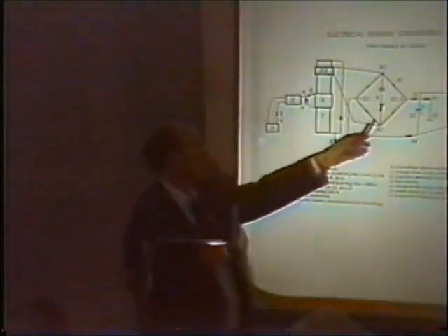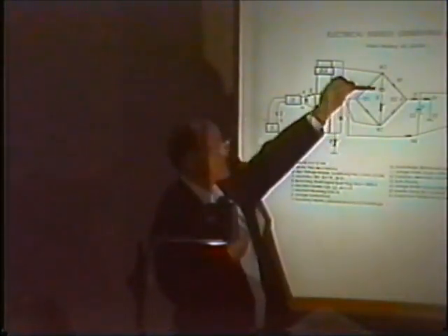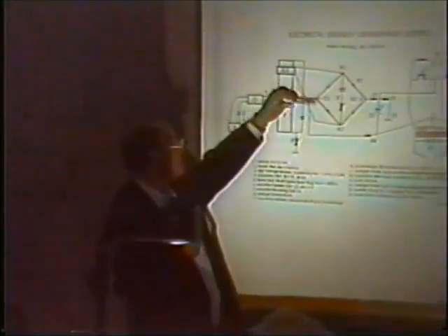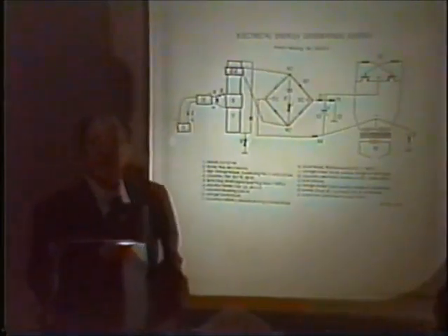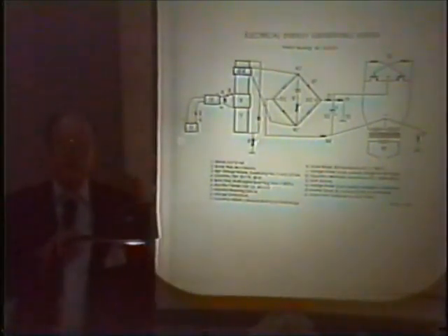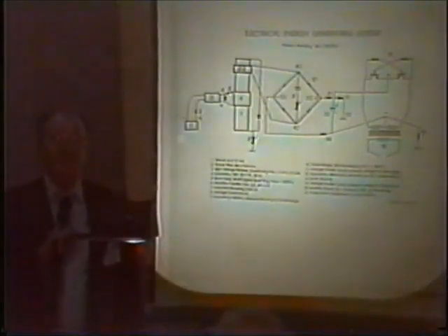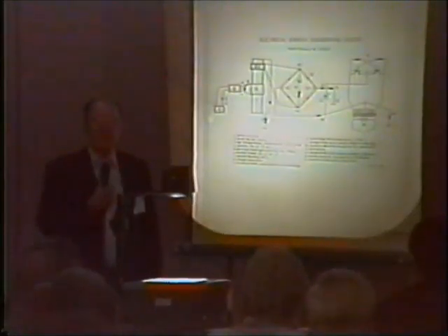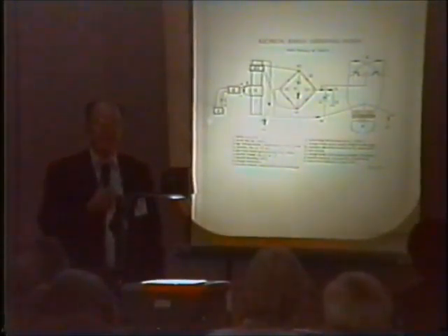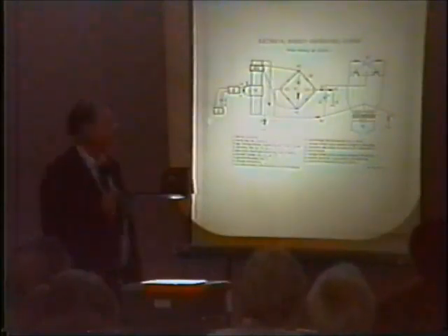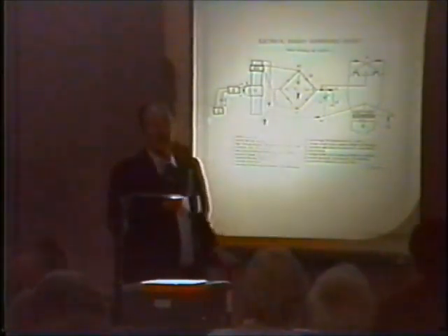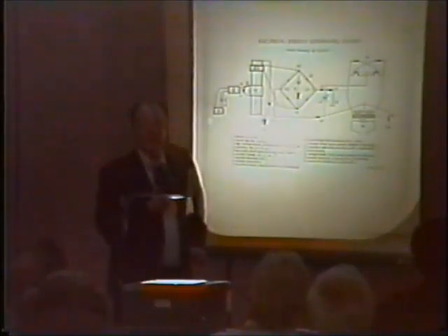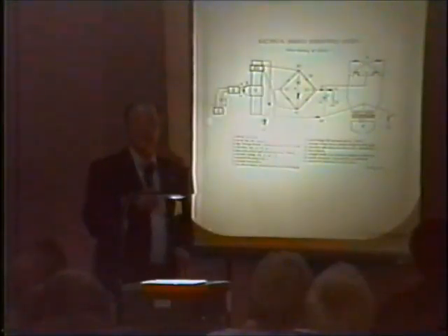Yeah, well, you've got voltage dividers. This is a frequency adjust deal here that if you need it, you may not need it. It depends on the input to the diode bridge. The diodes which I use are high voltage radio frequency diodes which show up in your television sets and things like that. They start at about 25,000 volts and go up, and 100,000 is not uncommon. So you've got, say, 4 of them there at 25,000 volts in the system, and they're radio frequency, and they'll operate very well, say, at 2 megahertz or 4 megahertz or whatever.